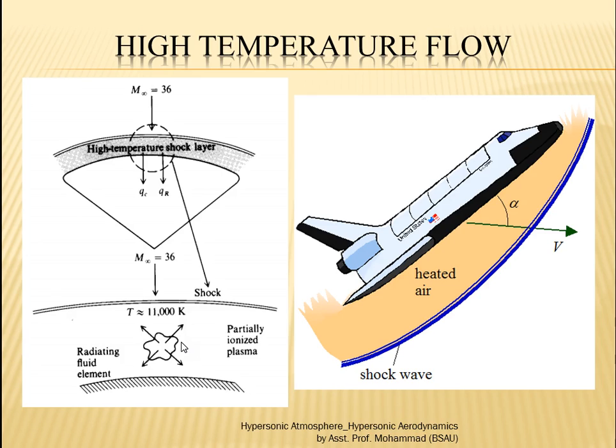So at this temperature, when we don't have constant properties, especially the specific heat capacities Cp and Cv, if they are not constant, then gamma is not constant, and if gamma is not constant, then whatever we estimate for the temperature and other things, depending upon the constant values, gives very unrealistic values. You'll see how unrealistic they are compared to the existing values.